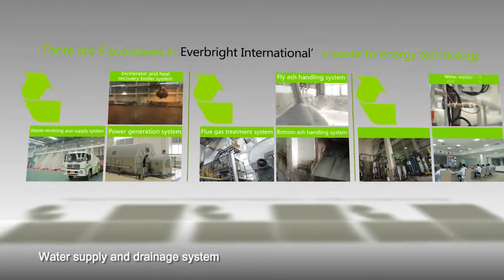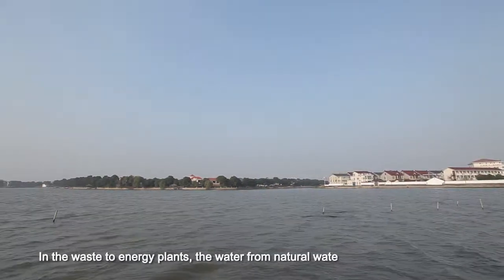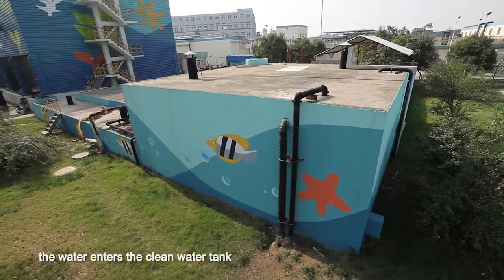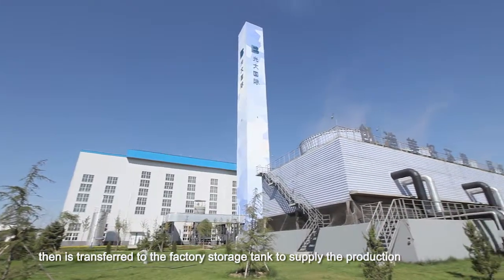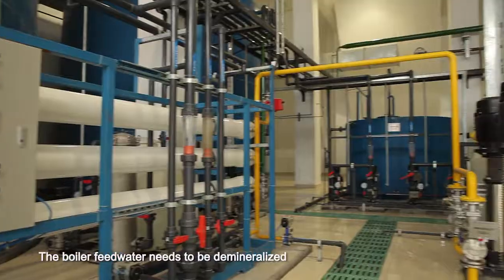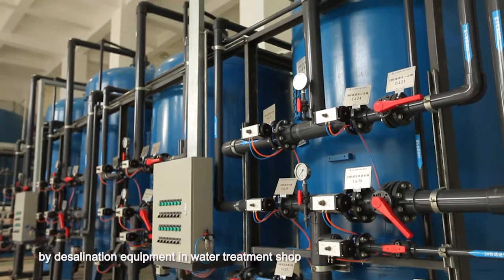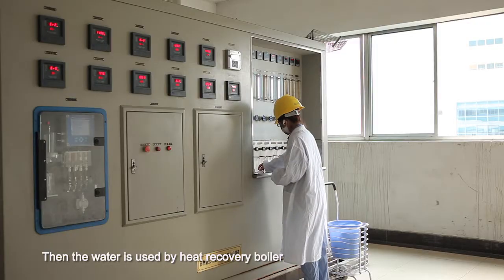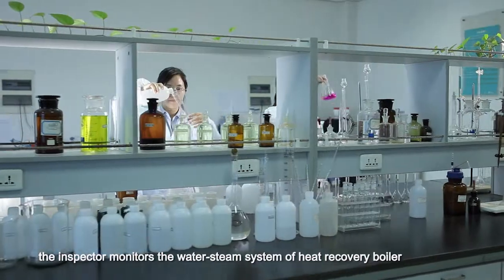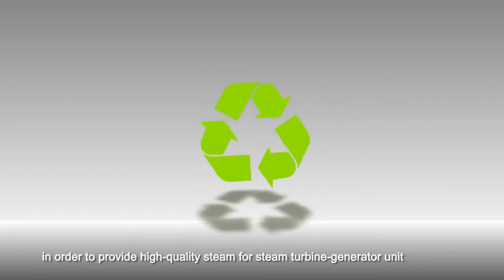7. Water supply and drainage system. In the waste-to-energy plants, the water from natural water goes into the integrated water purifier. After a series of treatment, the water enters the clean water tank, then is transferred to the factory storage tank to supply the production. The boiler feed water needs to be demineralized by desalination equipment in the water treatment shop. Then, the water is used by the heat recovery boiler. In the operation process, the inspector monitors the water steam system of the heat recovery boiler in order to provide high-quality steam for the steam turbine generator unit.